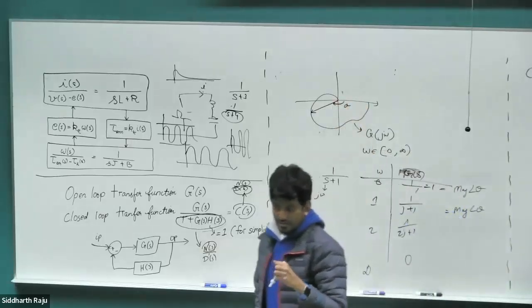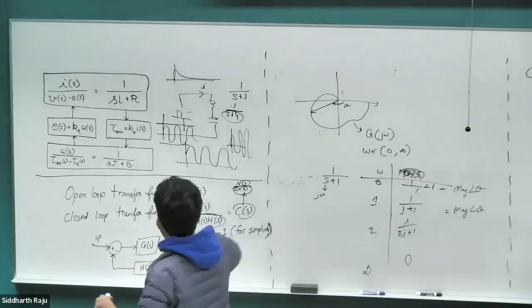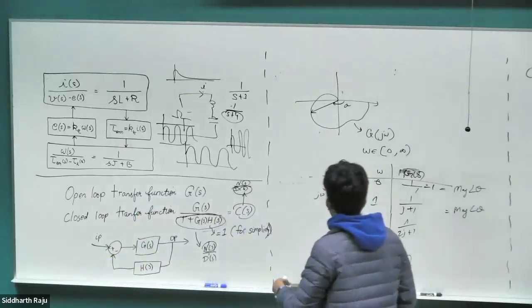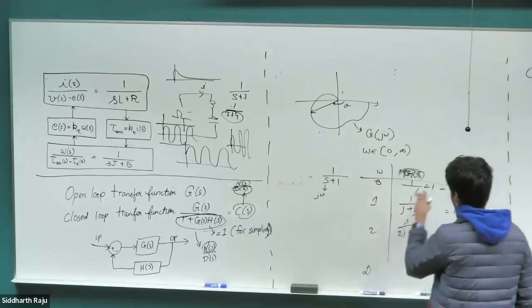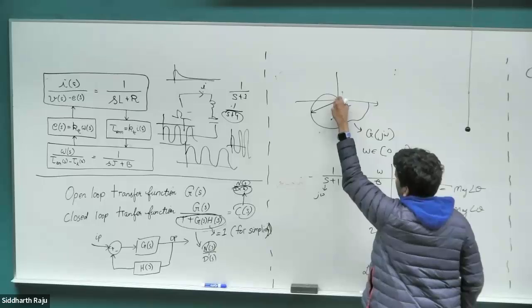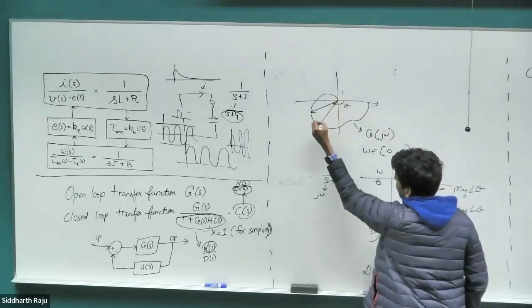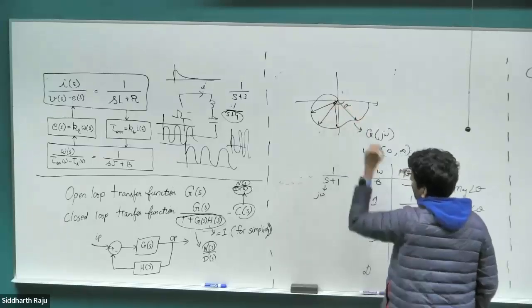Right? So when you talked about phase margin on the Nyquist plot, is that the same as the phase margin on the Bode plots? One and the same. And I'm getting to that in a second. So every single point that we have put here, we can substitute, get G of S values, and basically have the vector length and then the angle, so different values. So the first, second, third, fourth, and so on and so forth. Plot every single value and you get it.